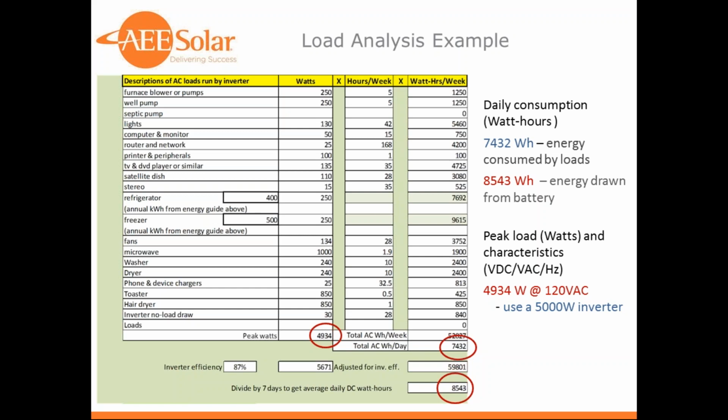We have to see what the solar energy potential is at the site, or whether there are other potential energy sources other than PV. Again, with the solar, you have to size the system based on the peak sun hours during the darkest month of the year, not the yearly average. We need to know about shade issues, mounting space.